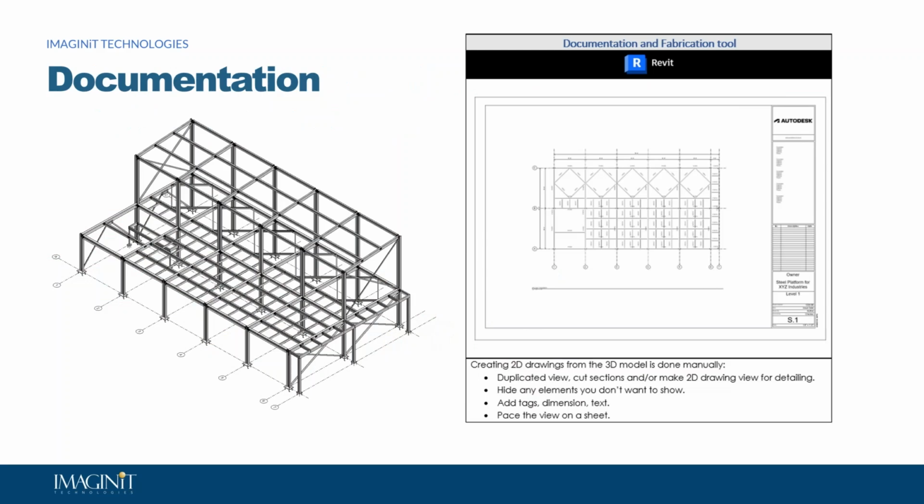Now, when I'm doing documentation in Revit, basically, I'm doing a lot of duplicating of drawings to make the views look different things. Maybe I want dimensions and tags in one view and not another. Then I make a sheet and I drag the view onto a sheet. And that's how we do it inside of Revit. So sometimes that project browser can get quite long of different looks that I want to see on different sheets, which is fine, it's good.